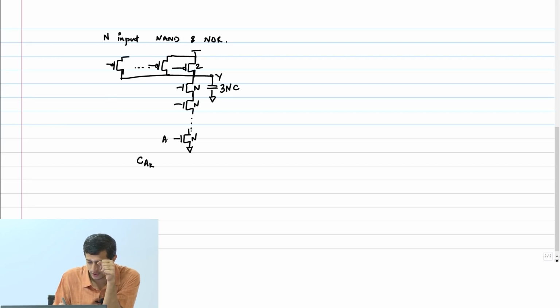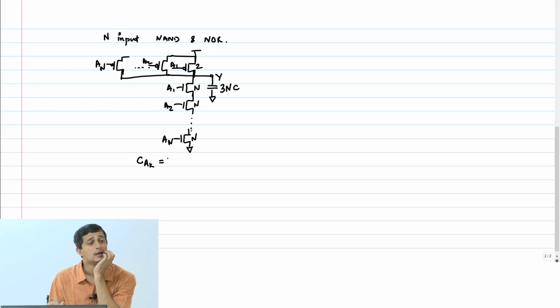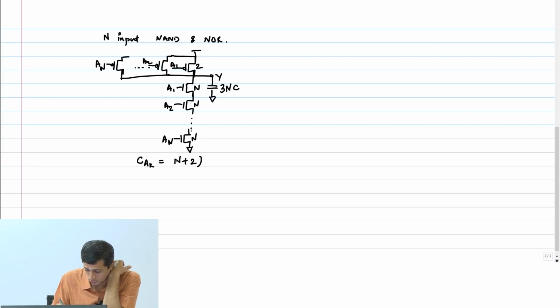So this is A1, A2, AN. It is N plus 2 into C. Therefore, logical effort on each input is N plus 2 into C divided by 3C.